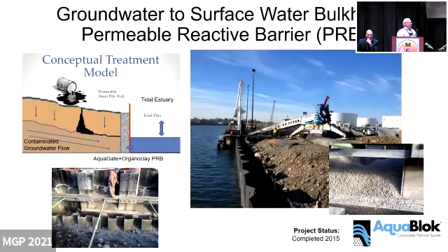So a couple of examples of this type of application. You can see here that this was a petroleum related facility where, this is kind of the CSM, you had the contaminated material that was in the subsurface. There's a sheet pile wall that has to remain permeable because they didn't want to create an issue with mounding of groundwater behind the sheet pile wall. So it was necessary to come up with some sort of a permeable absorptive material to limit the contaminants from reaching the water body.